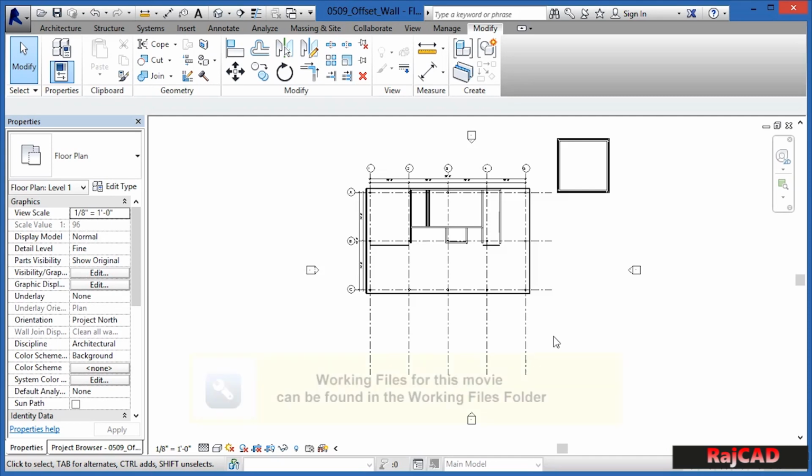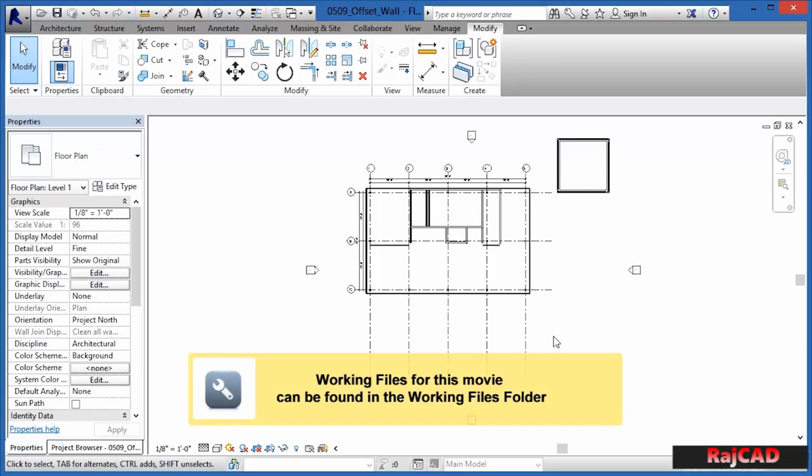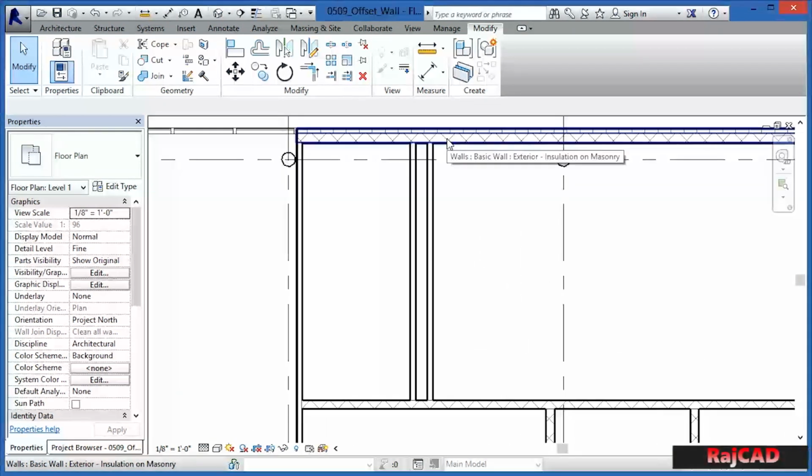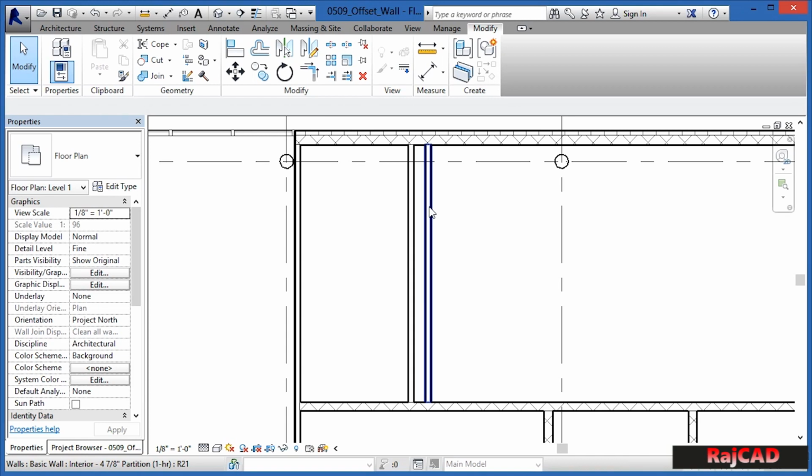If you need to make a copy of a wall an exact distance away from another wall, you can do that by using a command called offset. Now to execute that command, let's take a look at these two walls that are close to each other here in our drawing. What I'd like to do is make a copy of this wall here and copy it over to the right-hand side to make a similar space as to what we see over here on the left-hand side. And ultimately, these are going to be two different restrooms.